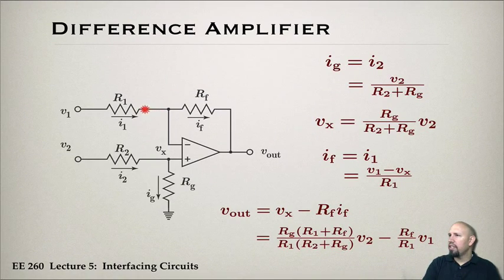We can also have a difference amplifier. So here is another circuit, and you can see it's getting more complicated. 2 resistors over here, 2 resistors here. We get this expression. So I'm not going to go through the analysis per se, but what I want to show is that we get this relationship. V out is basically given by this expression in terms of the resistors. So notice the sign of V2 and the sign of V1 are opposites.